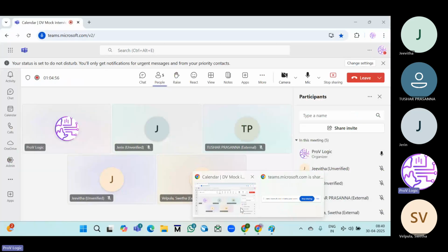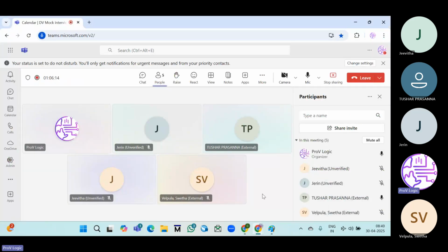Tushar, can you explain what type of circuit will be generated whenever we use case and if else? For case, it will be a regular mux, but for if else, it'll be a priority mux that will be generated. Priority mux. Okay.